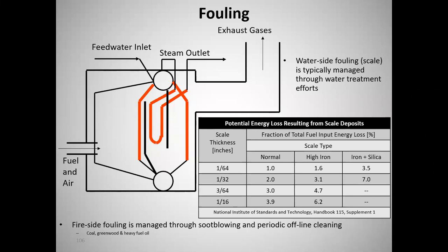So how can you damage a boiler tube? Well, the fireball is always 3,000 degrees. It's the water flow and the heat transfer to the water that protects the boiler tube. So when you go scaling up that boiler, you put this insulating blanket between the water and the wall, and you got the convection coefficient, and you got 3,000 degrees. That can't be good. It's not good, okay?